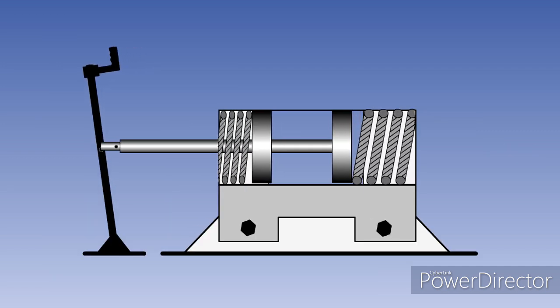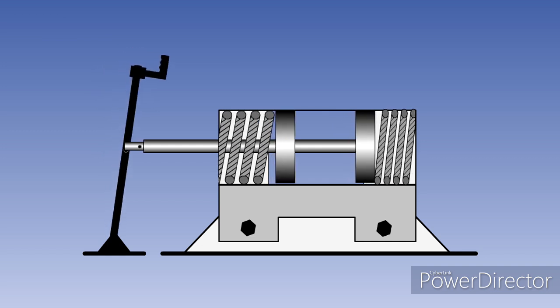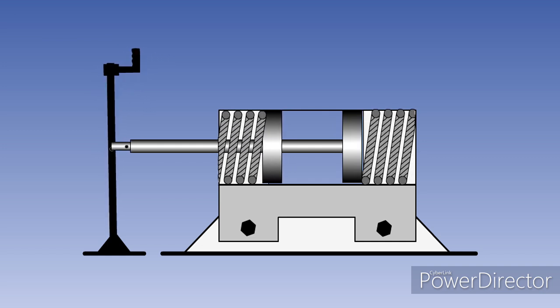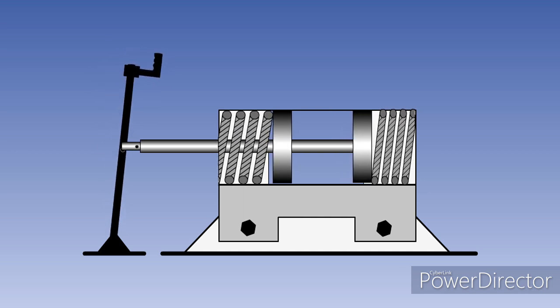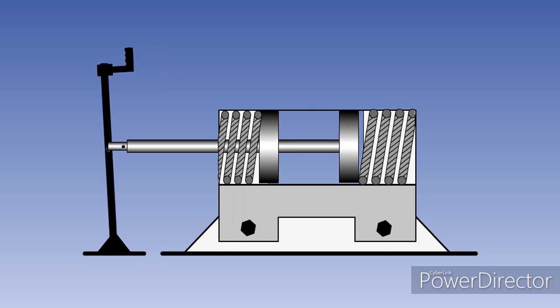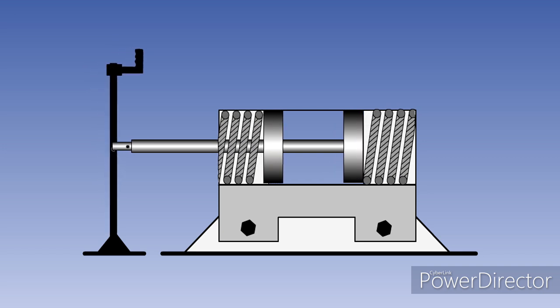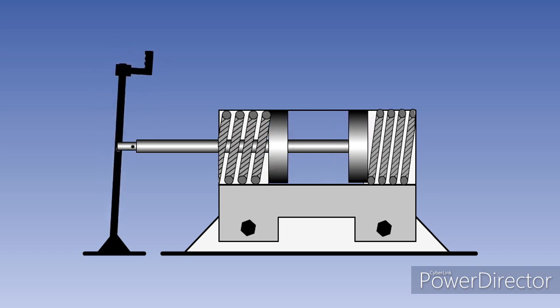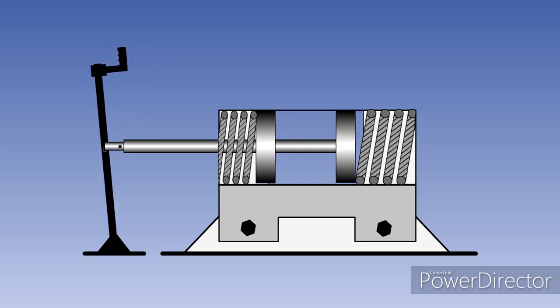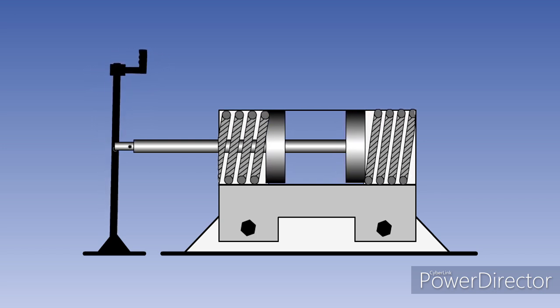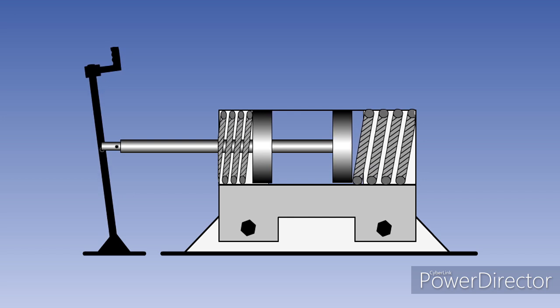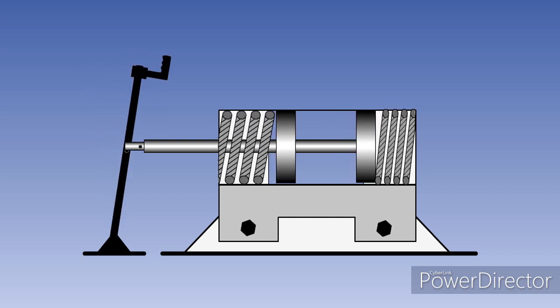The simplest feel unit consists of a box containing two springs, known as a spring box. Movement of the control column in either direction will compress one of the two springs. While this will give the pilot feel and will centre the controls when the control input is removed, the feel will not be proportional to the air loads. It will be the same over the entire speed range.